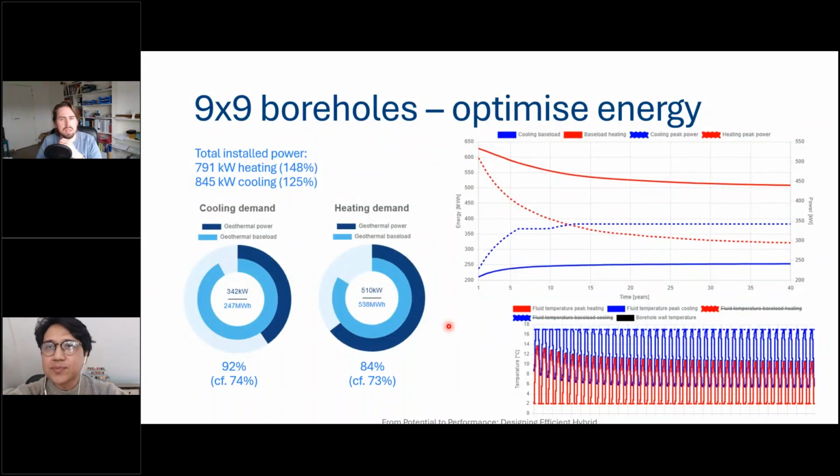So we have a very detailed way of putting in your borefield. Every borehole can have a different depth, different bury depth, different tilt, and different orientation. That's because of the beauty of these g-functions, which were developed at the Polytechnic University of Montreal. You can really model it as accurately as possible. We're not trying to find something that looks like it; we are really working with the design you enter. So yes, you can work with tilted boreholes in all different directions. No problem. Okay then.